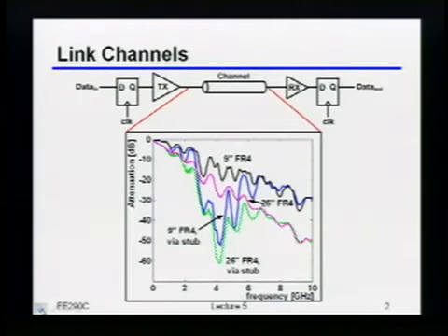What does this channel look like? Does it look like a first order low pass? Actually, there are 4 channels there, but do all 4 of them look like first order low pass? They don't, right? Even the one that kind of looks low pass has all this weird ripply junk on it. So if you wanted to build an analog circuit that was the inverse of that, how many poles and zeros would you need? Lots. Yeah, a lot. I don't know, but a lot, right?